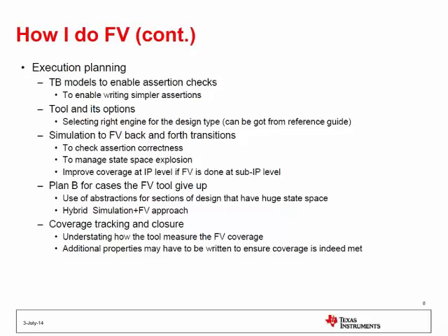And I think in the IBM presentation, you saw that hybrid flow, right? That's what we call state-based exposure. So you need to sometimes guide your formal tool to certain important states. For that, you need to have some simulation environment to guide it there, and then it explores from there. So to do that also, you'll need to fall back to simulation. And you may need to do some amount of coverage improvements.